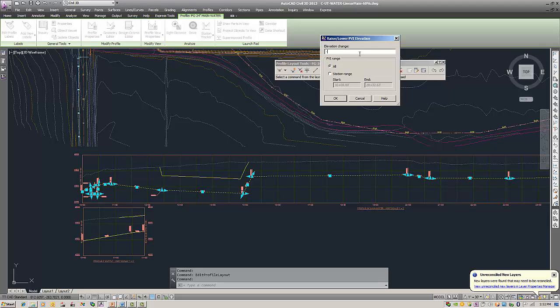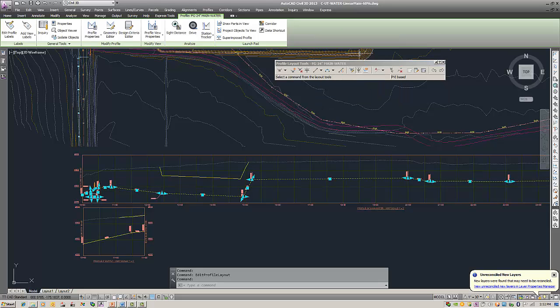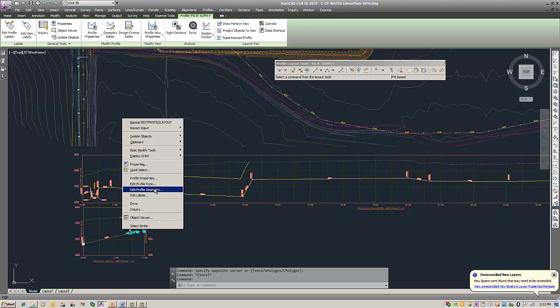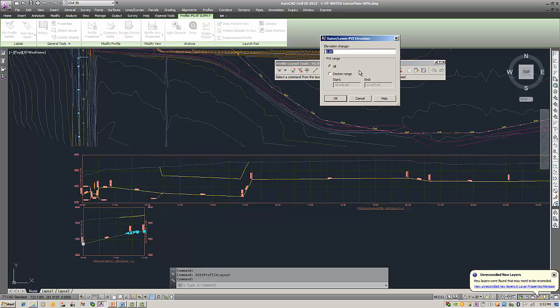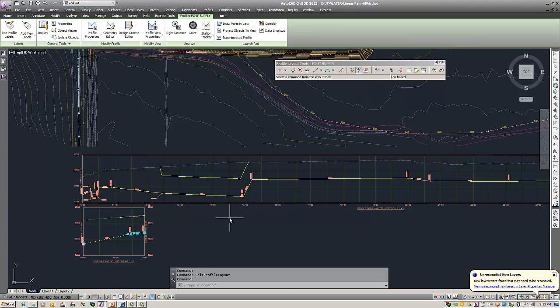So I'm going to bring it down -1 foot, so that way it drops it. As you saw over here, it dropped it here as well. This one's an 8-inch, so I'm going to edit the geometry again, make sure it changed to the appropriate pipe, and lower it by -4 inches or 0.33. So now that we've lowered our pipes, we are ready to extract that information.